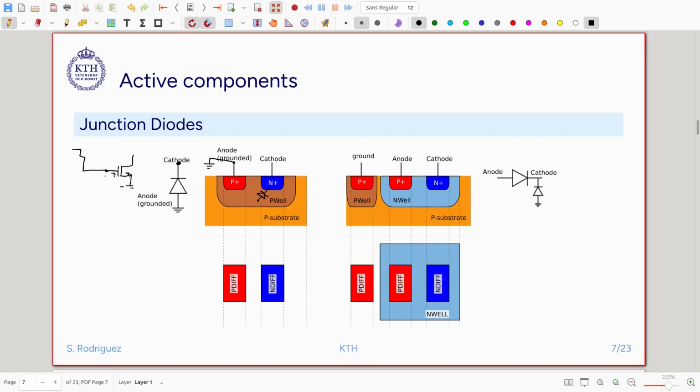And then to avoid that problem, sometimes we need to put a small diode here, reverse biased, so that the parasitic resistance of the reverse bias diode will discharge this line. Okay, it will discharge, and it will avoid that it gets to the voltage that damages the device. So it is working as an antenna protection. They may also be used as ESD protections, and then we will talk in the next course about how ESD protections are built, but they might also be used for ESD protections.